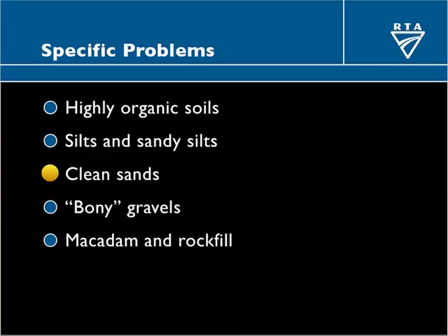Clean sands, which are quite different in their behaviour from most gravels or most soils, often have to be compacted almost bone dry or very close to saturation with vibration in order to get them down. Now, in that case, anyone who's been to a beach and tried to build a sandcastle will understand the difference. It has to do with the resistance of the material to compaction and to its shear strength.